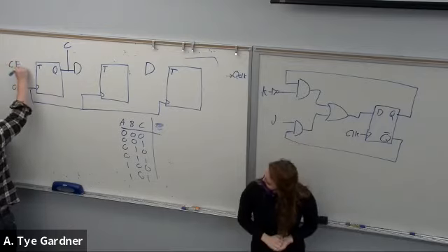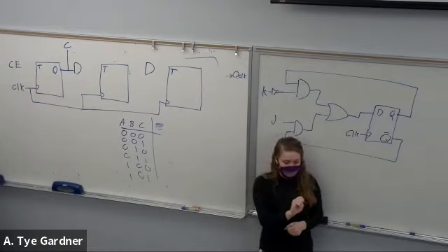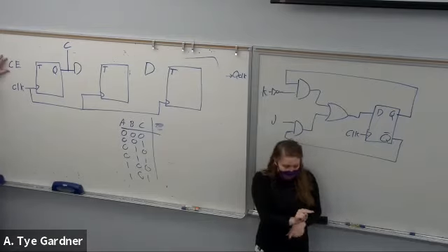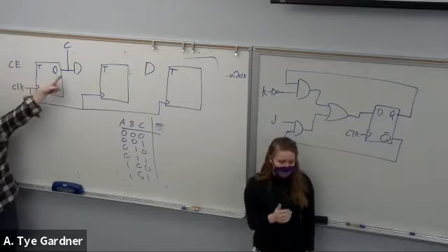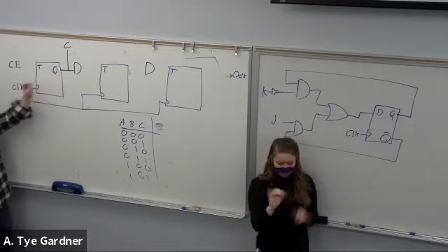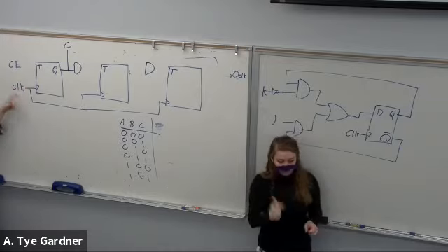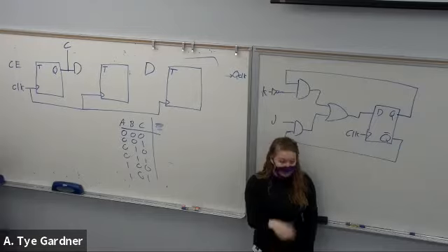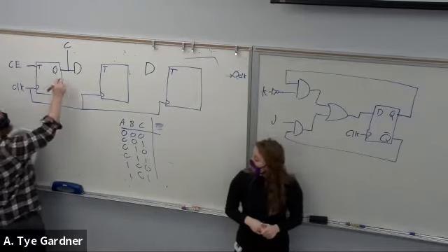Now I'm going to use this label of clock enable, meaning if the clock is on. So the reason I'm calling it a clock enable is because if it's 0, we'll never toggle. We'll never have a change in C. All right, so if it's 1, C will change every time a clock happens, except for we already know, well, I'll get to that in just a second.